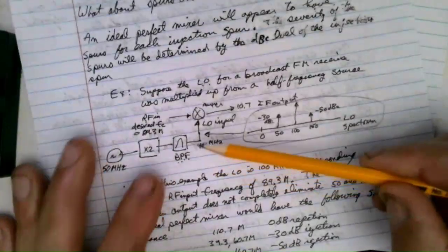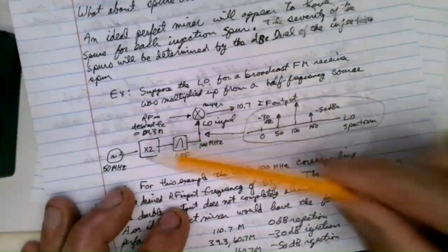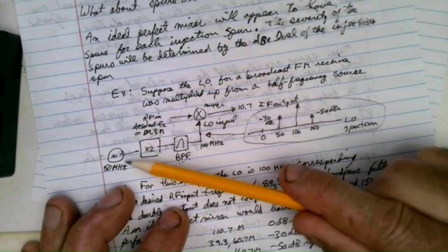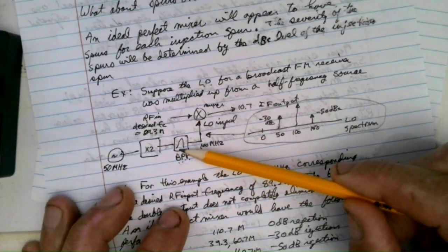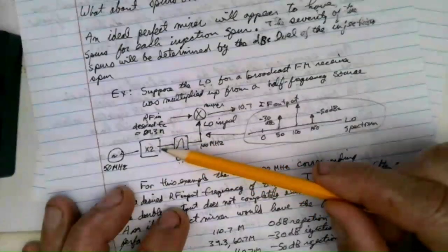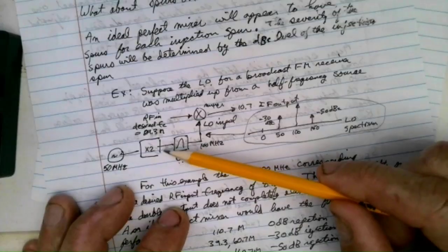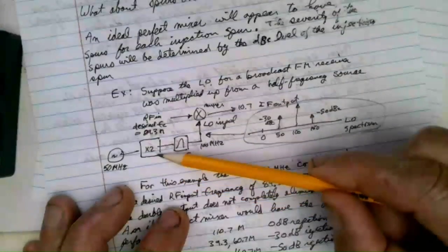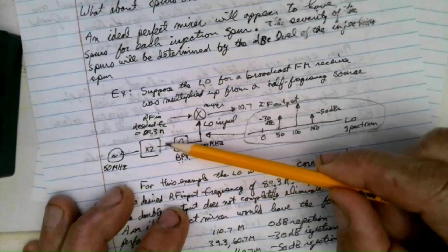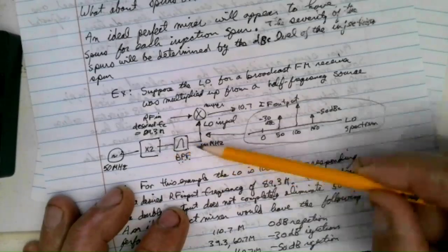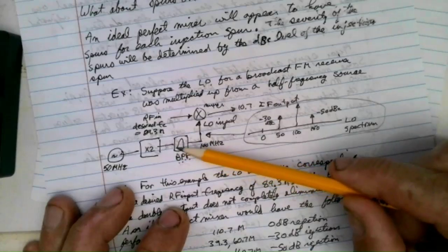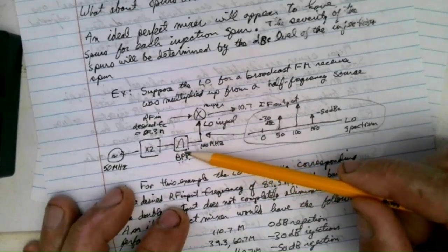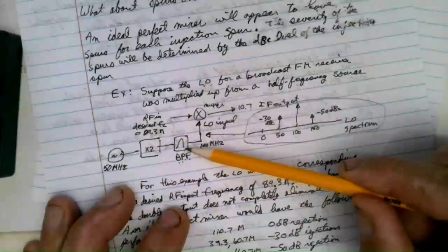That's our desired signal arithmetic. Now, let's suppose we choose to get this 100 megahertz by doubling up a 50 megahertz source with a doubler. And of course, then we're going to need a bandpass filter after it to clean up all the garbage coming out of the doubler. It's highly likely that the 50 megahertz output here will be more than the desired 100 megahertz, so we're putting a lot of strain on this bandpass filter to clean that signal up a little bit for us.